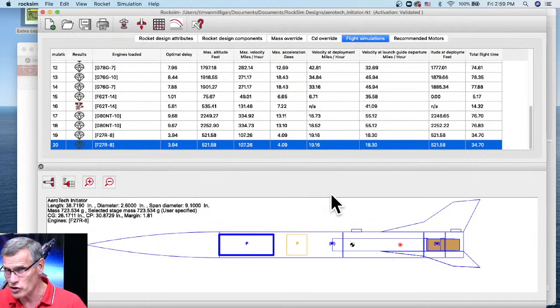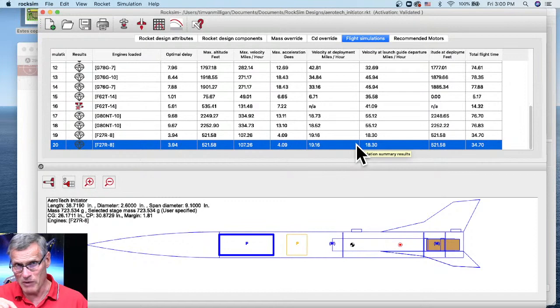So now if your question is, okay, if I have two parachutes and I want them both of the same diameter, but I do want them kind of like a cluster of parachutes, like when the Apollo came down, it had a cluster of 3 parachutes. And I think SpaceX Dragon also uses 3 parachutes. So what do you do in that case? The answer is you got to trick RockSim by making one parachute equal the same diameter as 3 parachutes. And this is a little bit harder.